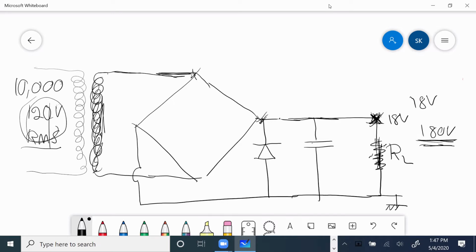In which case, that 18 volt can also go up, say, to 200 or something really ridiculous voltage high up. So for that reason, in order to prevent that voltage from ever exceeding 18 volt, I am going to put a Zener diode here of 18.2 volt, for example.